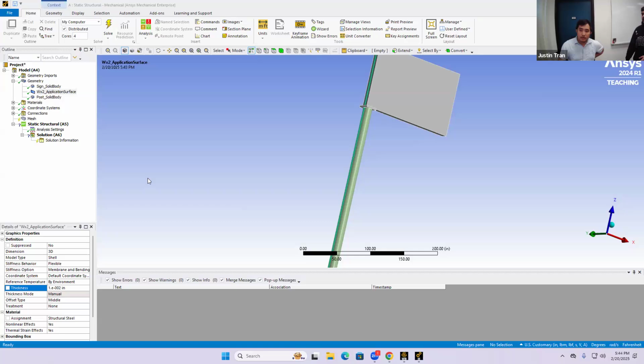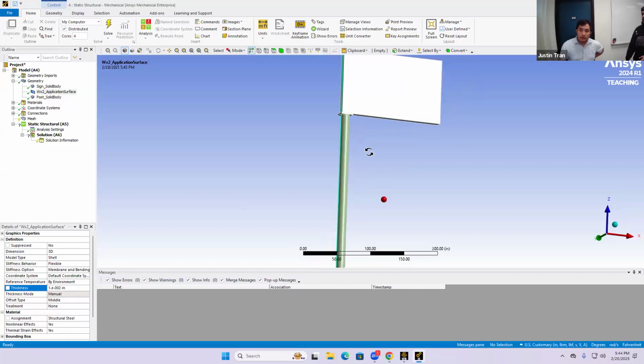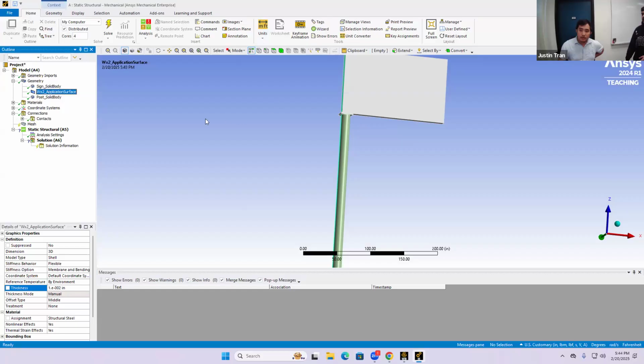the different parts. Okay. And so when you have an assembly of parts like this, it's actually possible for these parts to slide past each other in the ANSYS simulation. Okay. So there's a lot of cases where you're simulating an assembly of different parts, and two parts may have some kind of connection where they can either slide past each other or rotate past each other. And there's a way for ANSYS to actually account for that as well. Okay. So to look at the connection between the parts, you're going to open up this window on the left-hand side called Connections. Okay. And then you're going to open up the next submenu there called Contact.